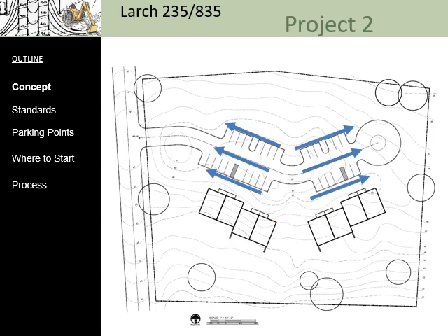And this year, we're going to basically show you how you're going to have to drain this parking lot. This is going to save a lot of time for you as you struggle to get through starting on the concept of this. So it's fairly straightforward. You've got parking lot, it's going to drain away. This is a natural high point in the middle, and that water is going to drain away from the center portion down the parking lots and out into the site. You will, of course, have to drain some water around the buildings. We're going to discourage you from draining water between the buildings, as we discussed in a previous exercise.